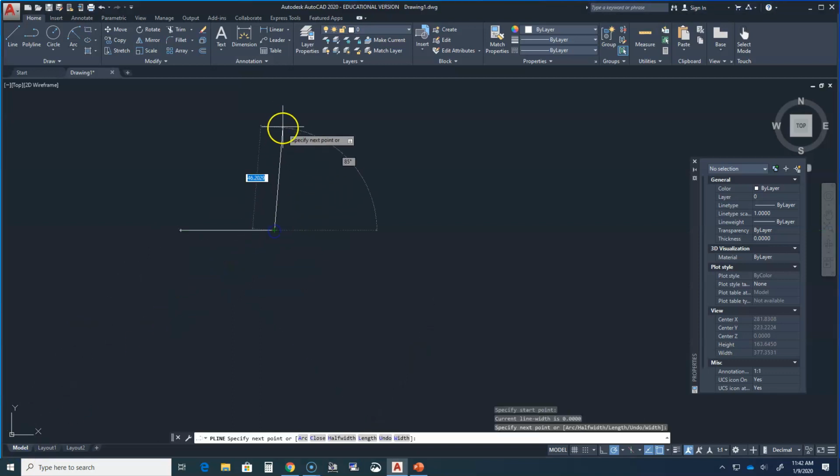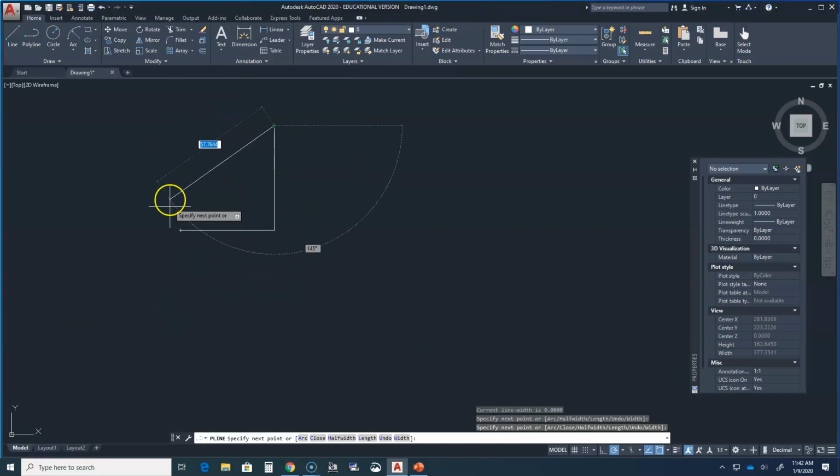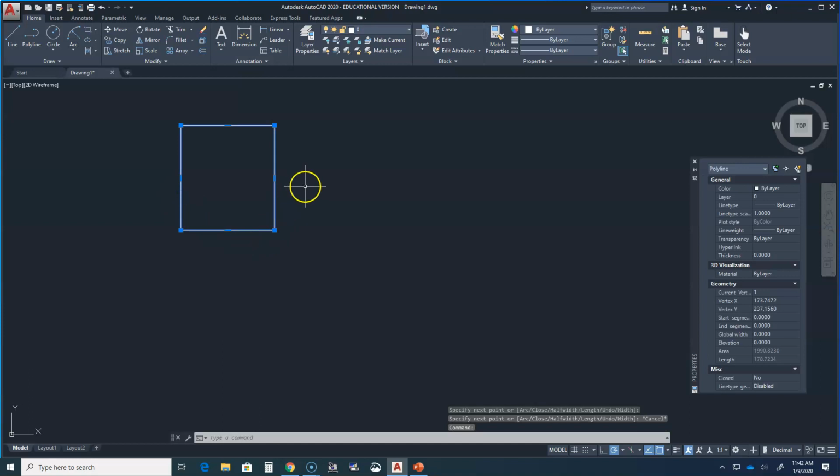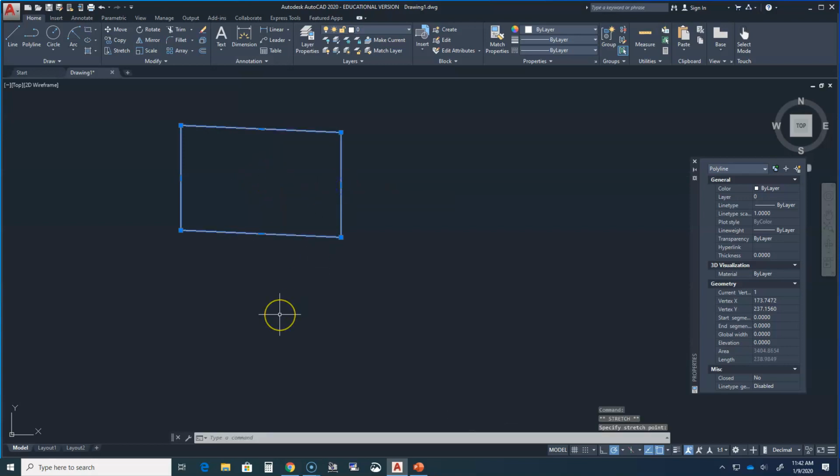Go ahead and draw a square of any size, then escape from the Polyline tool. Select the square you just created. The whole square should activate and show grips at all apexes and linear grips on all sides, which can be used to modify the shape. Pretty simple so far.